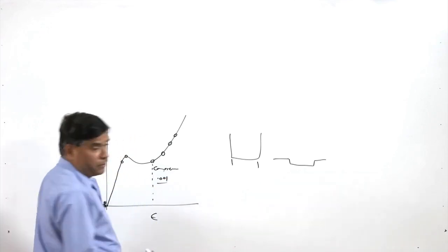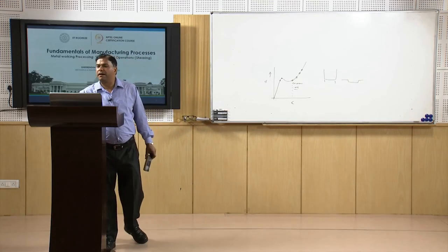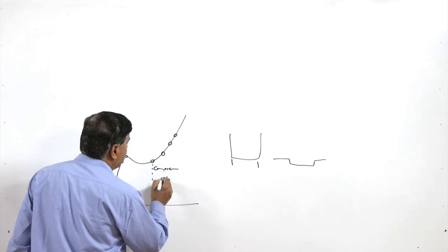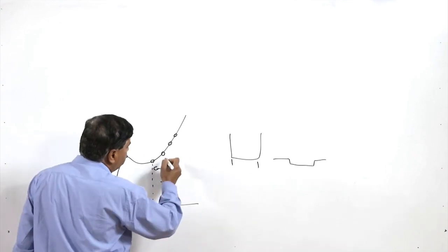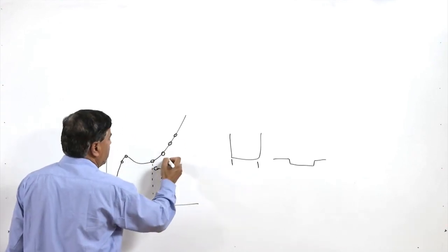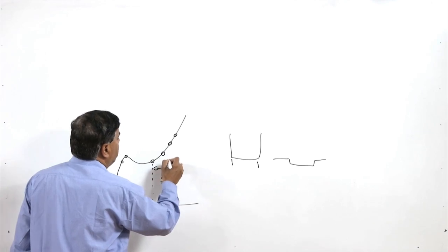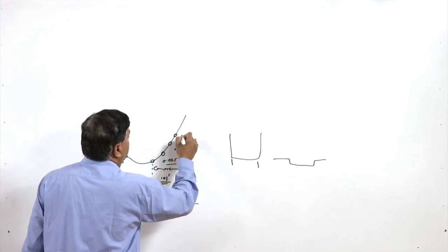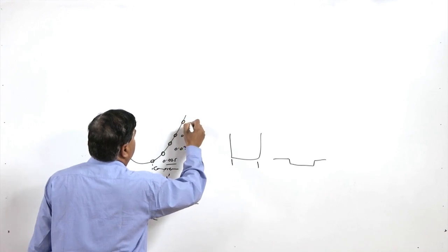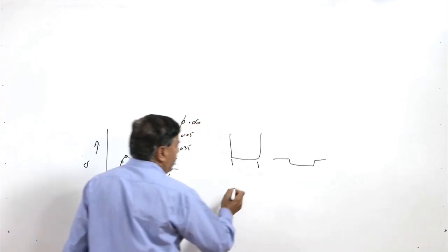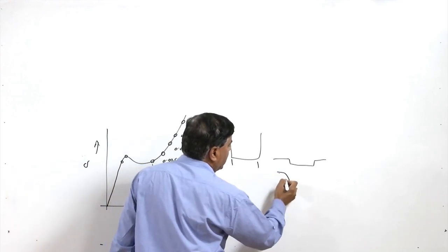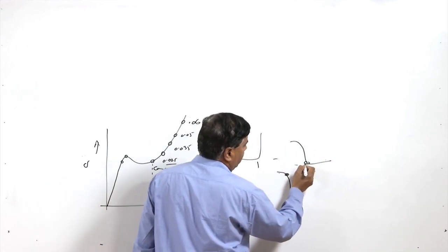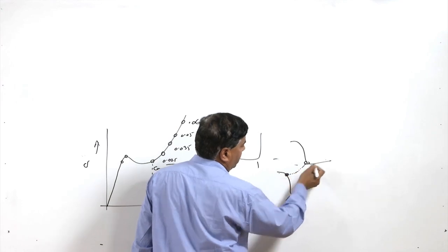0.01 inch. So, for the smaller magnitude, the initial entry causing a depth of 0.01 inch, when the depth increases obviously the compressive strain and stresses will keep on increasing. So, they will be causing more compressive strain, say this will keep on increasing like this, and after reaching a particular value, say 0.05, we will find that the crack nucleation will start from both the sides, from the lower side as well as from the upper side like this. So, from this end the crack will start propagating, and from this side the crack will start propagating, and both will meet